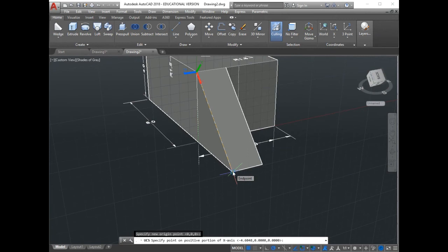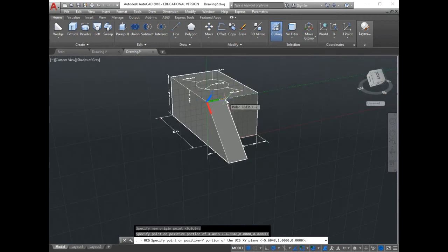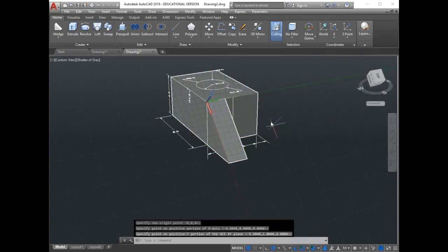Extract edges. It will make your life easy. And by the way, when you make extract edges, no need to activate the 3D object snap. Only 2D will work with you. Okay, so you pick up this one and then simply pick up that corner there. If it does not work, I can go for the all the way to that side. Clear, guys? Here you go.